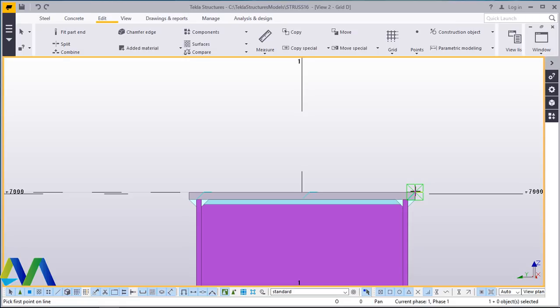You'll struggle a bit to define your straight line. Now on TEKLA Structure 2017, the moment I click here and give it an orientation as a straight line, the line will be straight like this. It snaps on 90 degrees. I'm comfortable with that direction and that straightness of the line. I'll just feed my measurements of that line as 600 and enter that.